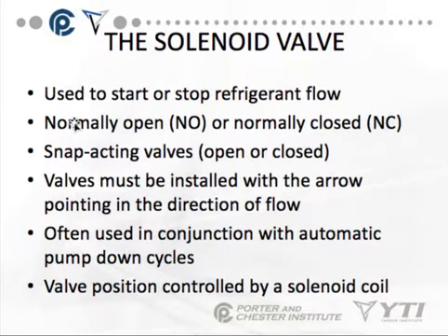Okay. The solenoid valve is a liquid line solenoid valve or a defrost valve that's used to start or stop refrigerant flow. They come in normally open or normally closed, and they're snap acting. In other words, they're very fast, open or closed. You have to be very careful if you're installing these as replacement valves, because they have to be installed with the arrow that's printed on them in the direction of flow. Do not use them in reverse. They will not work. They're often used in conjunction with automatic pump down cycles.